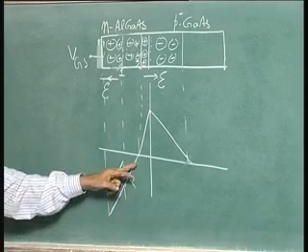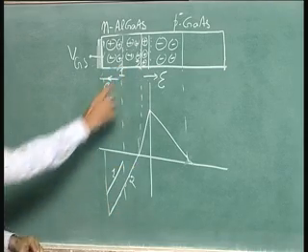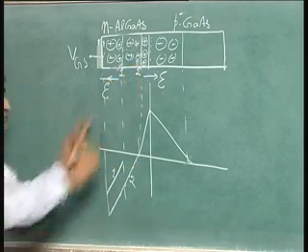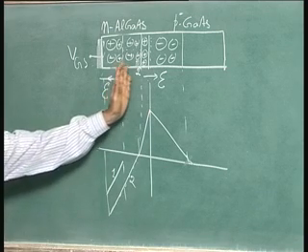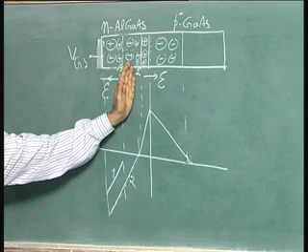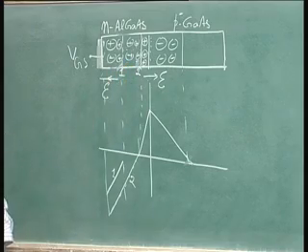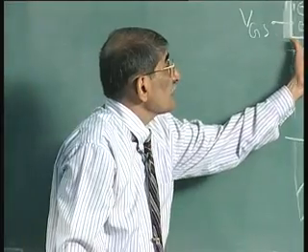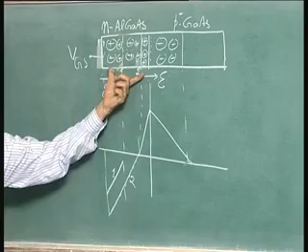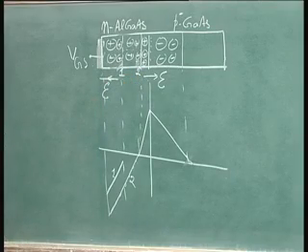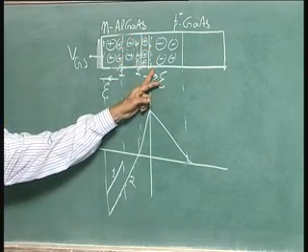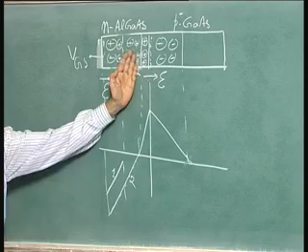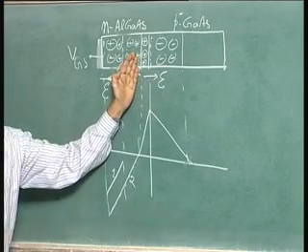Electric field line 2 corresponds to the situation when the depletion layer is at 2, in the sense that both the depletion layers have merged now. You can see that at a particular voltage VGS, the total layer is depleted, okay, but the charges are present here. The charges are present here, because that part you have not disturbed so far.